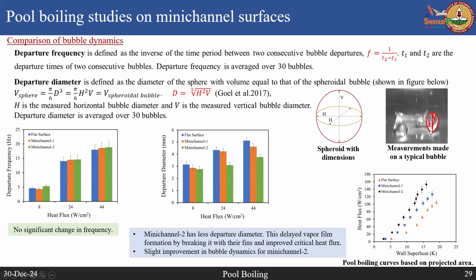So, if your surface is less wettable, like if you have a hydrophobic or a super hydrophobic surface, this angle will be much larger. Whereas in a highly wetting case, like this is a case where it is highly wetting, the liquid is able to form a smaller contact angle. If your contact angle becomes much larger as in a super hydrophobic case, then this elongation will become much more, because the contact angle will be much larger and this departure will become much more from the spherical shape.